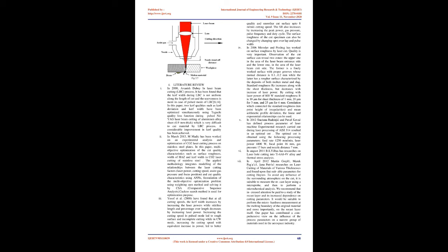3.7 Nozzle diameter and standoff distance. The nozzle delivers the cutting gas to the cutting front, ensuring that the gas is coaxial with the laser beam and stabilizes the pressure on the workpiece. The nozzle orifice determines the shape of the cutting gas jet and the quality of cut. Mainly the diameter of the nozzle ranges from 0.8 mm to 3 mm. Due to the smaller size of the beam, the cut kerf is often smaller than the diameter of the nozzle.